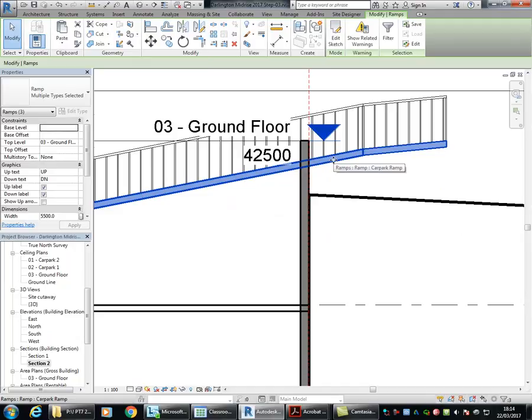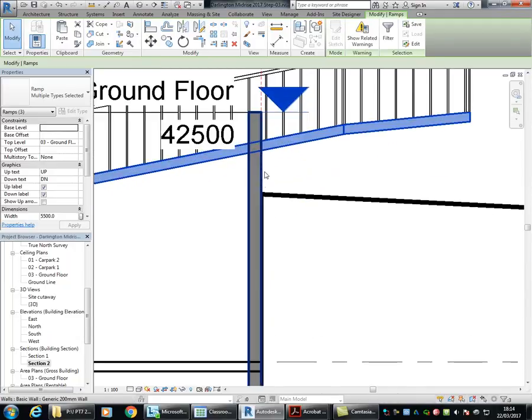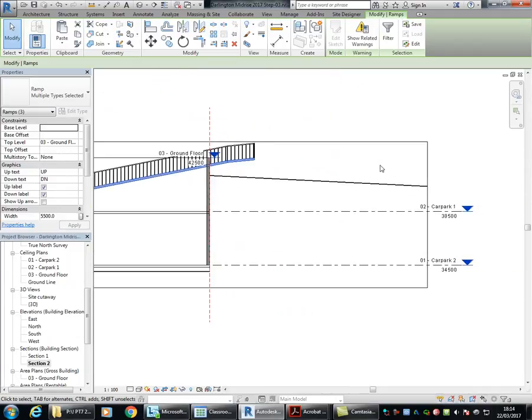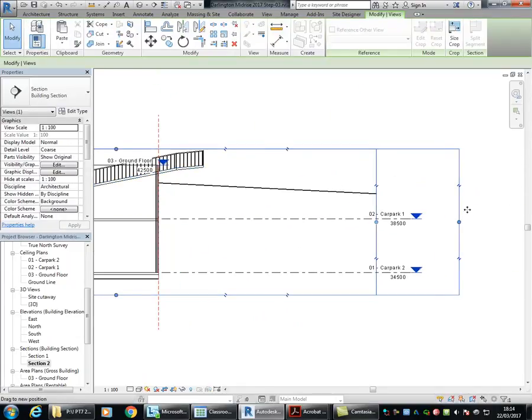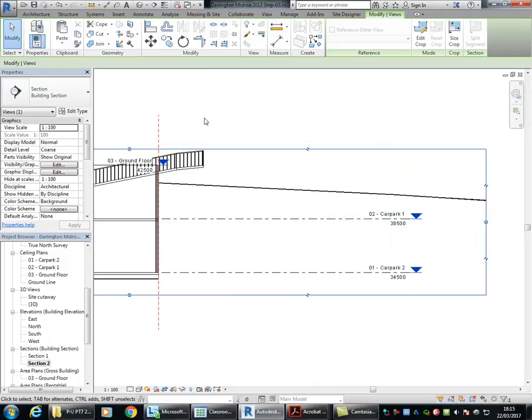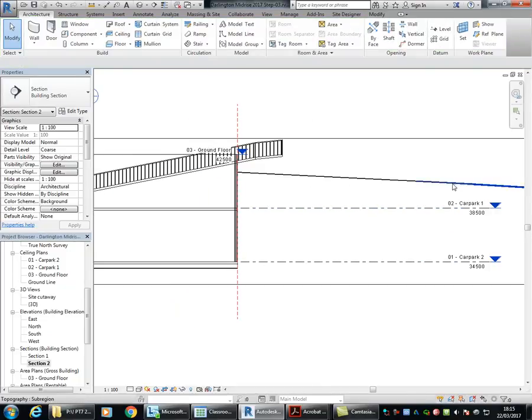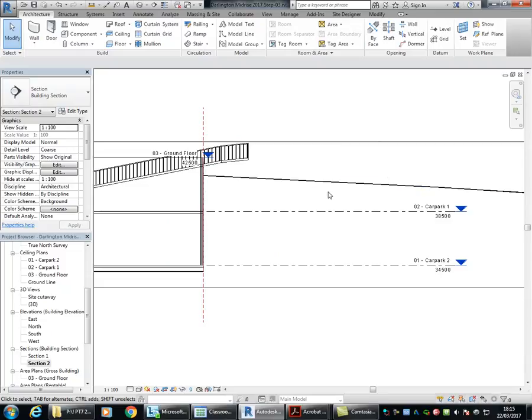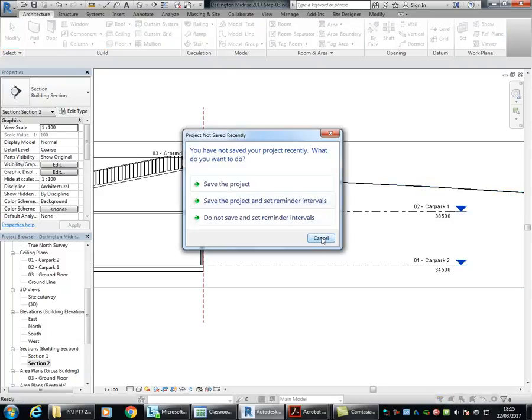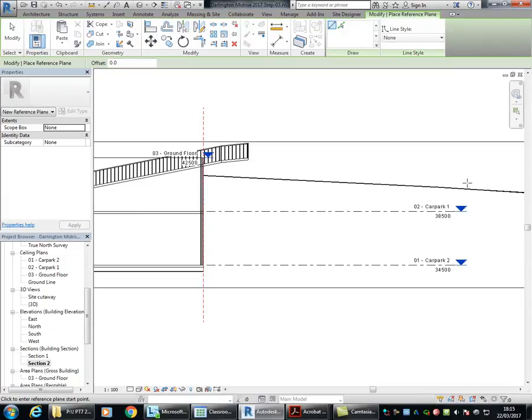Now, looking at the ground though, obviously this is the highest point that you'd need to access the car park, but remember that the boundary is out here somewhere, and that's obviously lower still, and so you can easily have a ramp, probably with a lesser gradient, that's excavated into your site, and this is normally what you'd have to do. So you'd have a slope, and I think this is why probably when you're doing it at the garage you would have come up with a bigger ramp than you need.